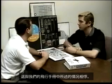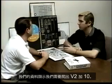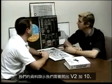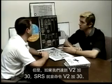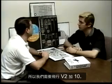You have to remember that this kind of goes against what our profile says in the flight manual. Our profile says that we need to climb out at V2 plus 10. SRS, though, if we got to V2 plus 30, it'll command V2 plus 30. So we need to fly V2 plus 10.